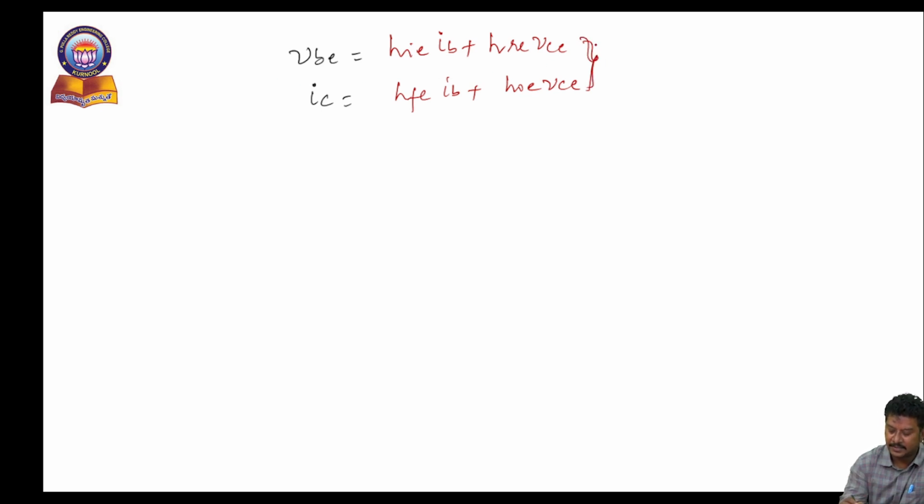The first equation obeys the principle of Thevenin's equivalent, and the second equation obeys the principle of Norton's equivalent. According to that, I frame the internal structure of a transistor using a dependent voltage source and dependent current source, consisting of the input side with a resistor and the output side with a parallel resistance which is parallel to the dependent current source.